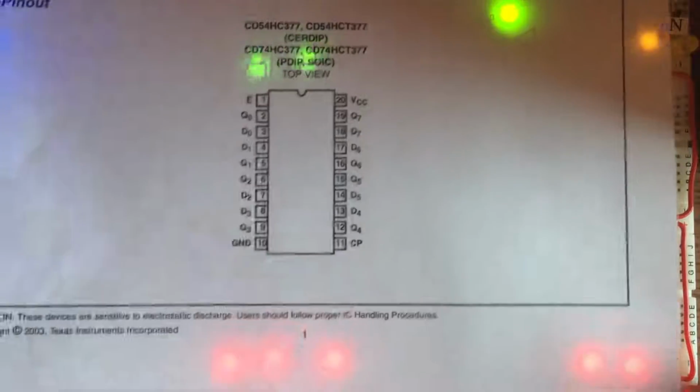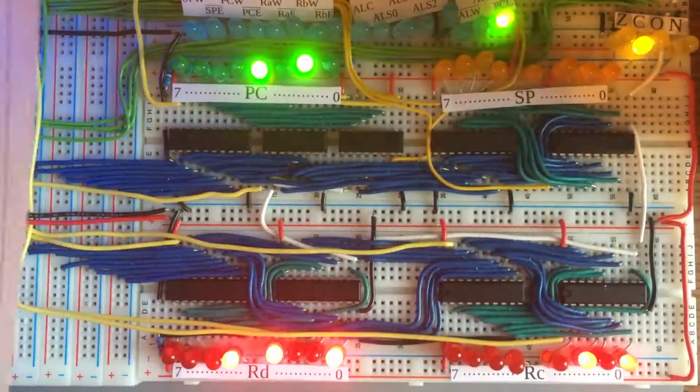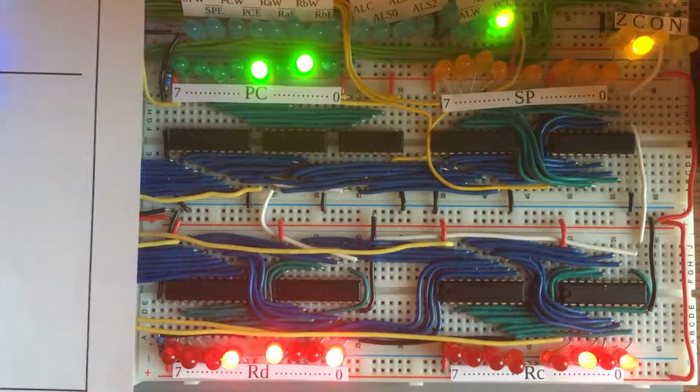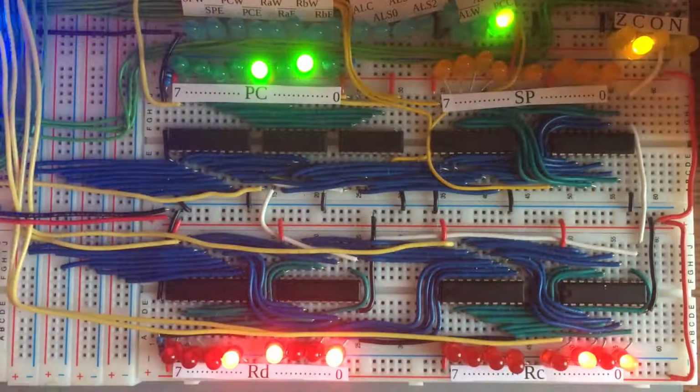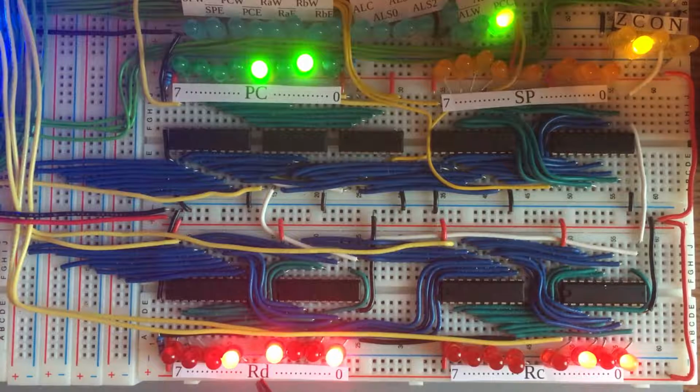And that's actually good, because if you look back at Ben's videos, he uses the 74LS173, which has an output enable signal, and he needs to activate that permanently, because we want to see the value that's in the register and show it on here, even if we're not outputting on the bus. So right now, the bus contains some totally different value because it's not being enabled at all by the D register. But the D register still has a value, and we would still like to see what it is.